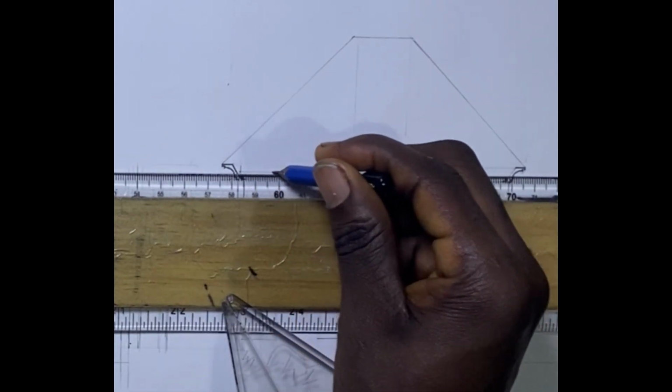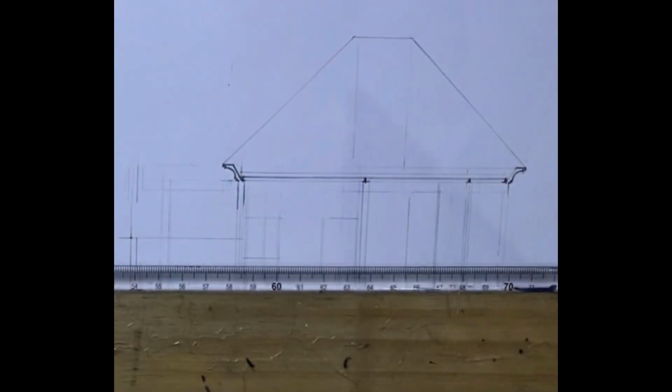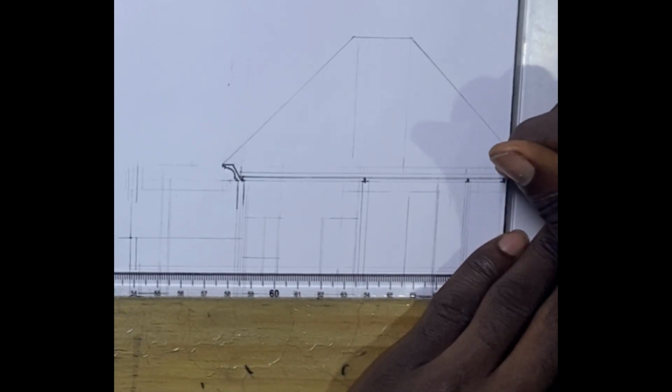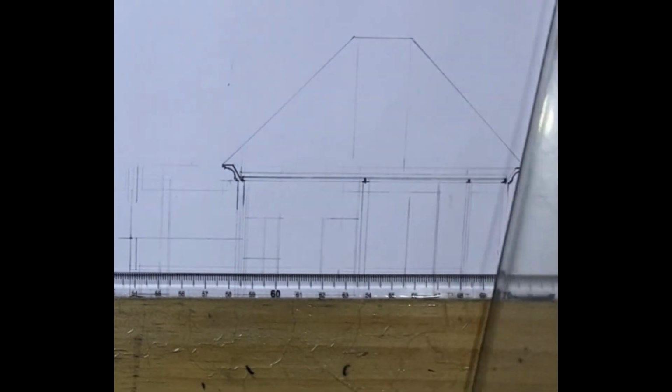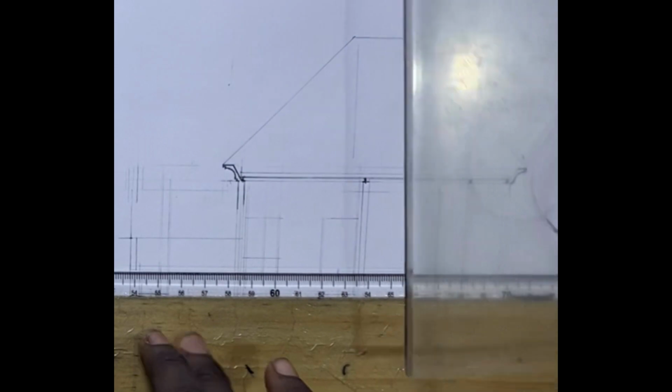And do ensure you use a thin continuous line because we are going to be showing some detailings. Detailings are not meant to be hidden, they are meant to be seen. Thereafter, we start from the center. We all know that the highest point of a roof member is being held by the king post. We have the king post, the struts, the tie beam, the purlins, and the rafter of the roof member.